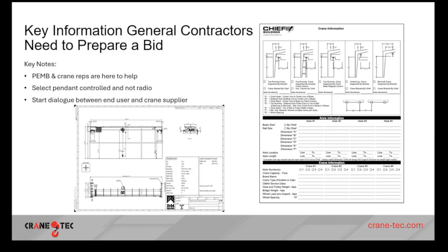That's information that you're going to need to have from your customer that they need to supply to you so you can properly fill out this crane data form. It's very often where you have 2 10-ton cranes on a runway and it's 25-foot building column spacing. And if you have 2 10-ton cranes, there's no limits between the cranes. And so the runway needs to be designed for 20-ton. Does that kind of answer the question you were looking for, Larry?